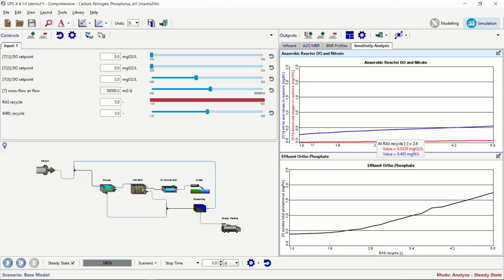And the DO has come up from basically negligible to, well, maybe not so negligible anymore. I mean, it's not high, but it's also not 0 either. So what we were telling him, or what we were able to see as a group together playing with this model, was that there was a big impact of recycling from the 3rd, the aerobic zone, all the way back to the anaerobic zone.